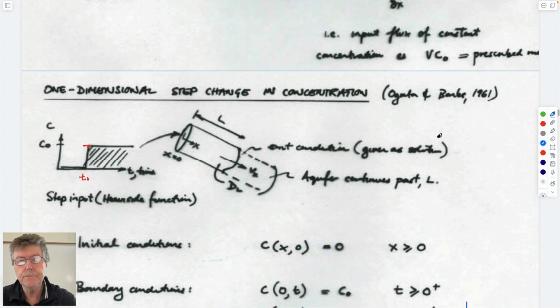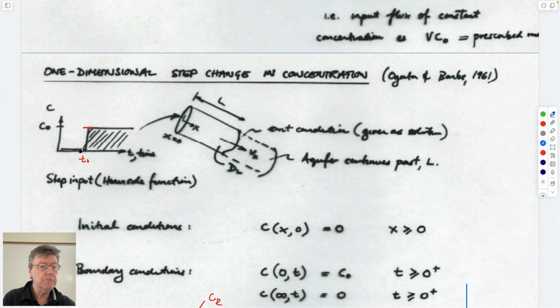residence time distribution. So if this is the upstream behavior, there's the boundary condition. This is the behavior in the core. You'd expect that if you looked at the concentration as you go downstream it would look like this. This would be X, this would be C over C0, this would be 1, this would be 0.